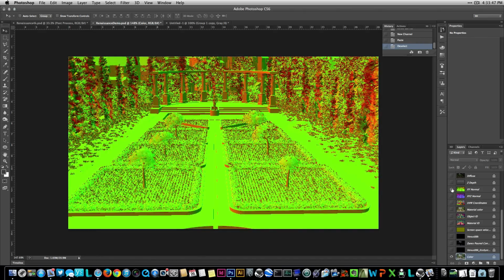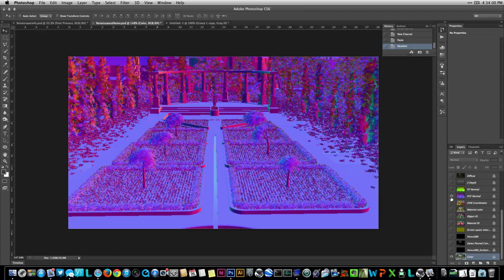See, we've got XY normals. So this is basically the stuff on the left is red, the stuff on the right is green. And of course, flat stuff doesn't really come into it. That's what XYZ normals are all about. The cool thing with this is that, let's say I wanted to select all of the faces in this direction.